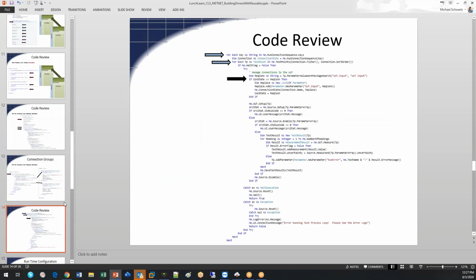So next, as we get in here for each one of our loops, we're going to check our connections. If we're running like a multifunction calibrator, we might be telling them put the short on channel 1, put the short on channel 2, put the short on channel 3 if we're doing like an O-scope. That's where they'll get those connection changes as they're running through their data points. And if they had to connect it to each one of the voltages, they could run either a 9500 doing a 4-channel configuration, because they would have a 4-channel connection message here, or they would run them a single channel at a time.